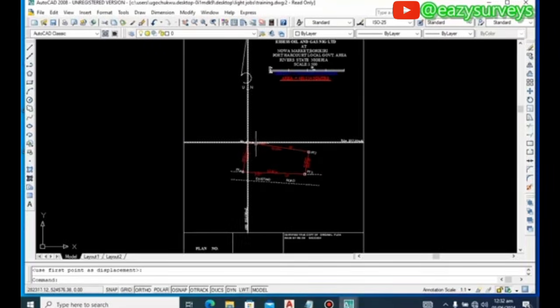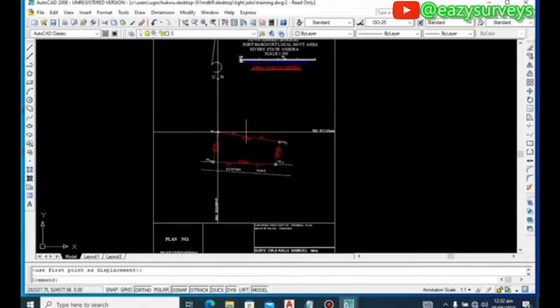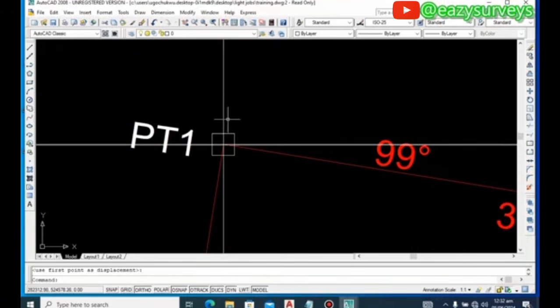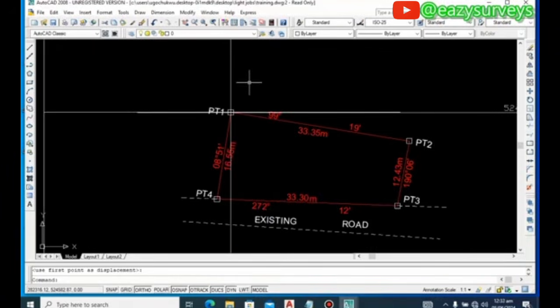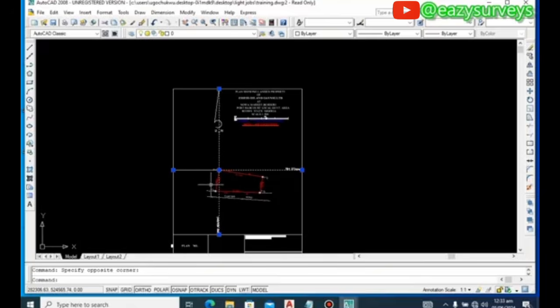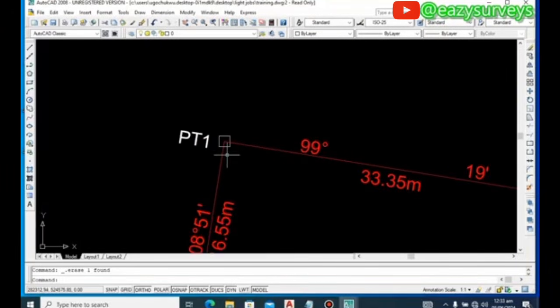So I have successfully aligned the true north and the coordinates to the origin points. Now I'm going to delete the polyline I used to align my true north. Then the very last thing is to use the same auto mode to show the cardinal points.